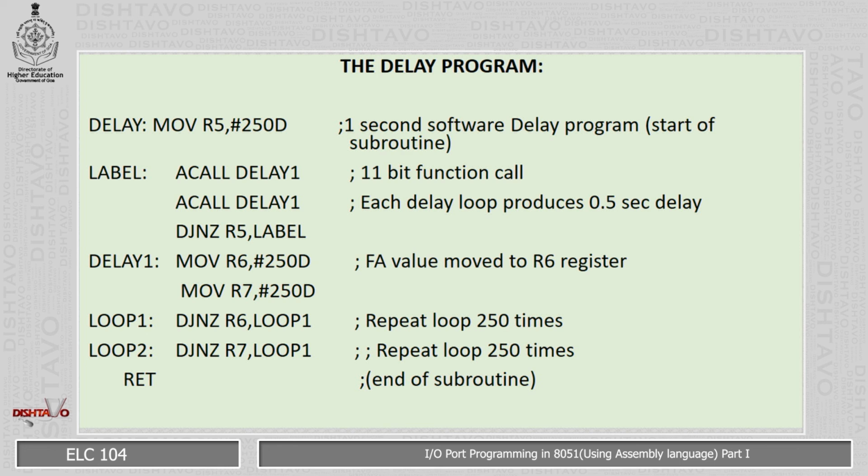Whenever we call a subroutine, it will go to a particular area in the memory. That location is given by your absolute call. It will take the address of the program counter plus the address of your absolute call, combine them together to form a particular address, and then jump to that address. This is a bigger topic that will be discussed later on.